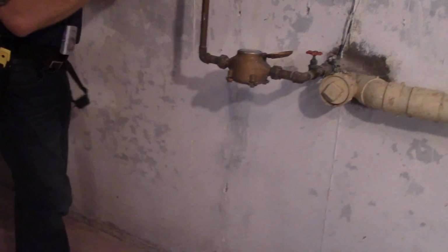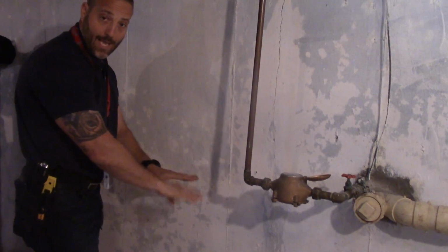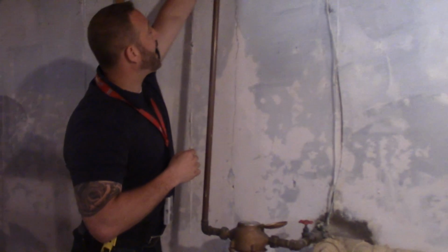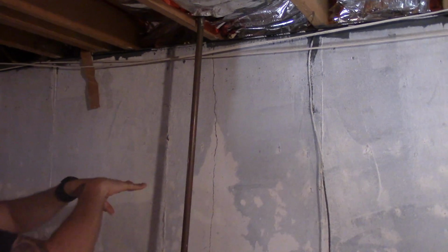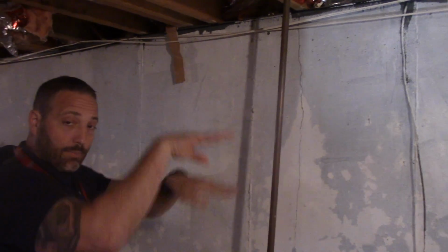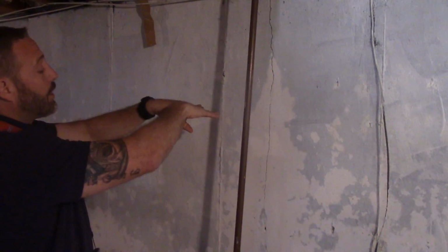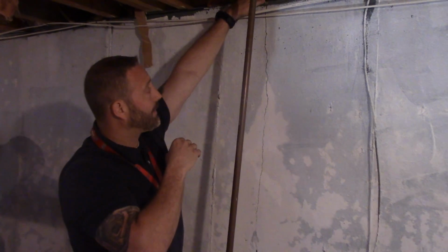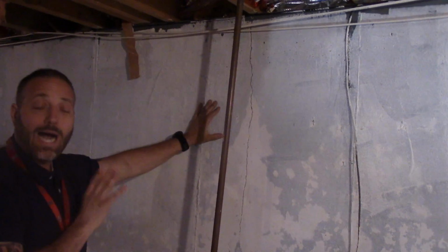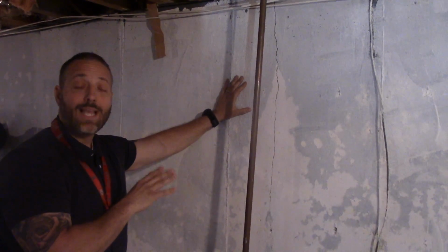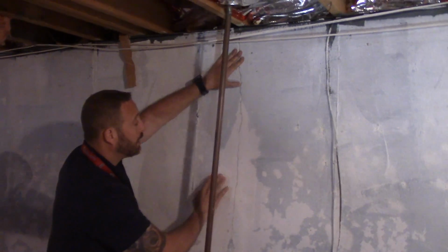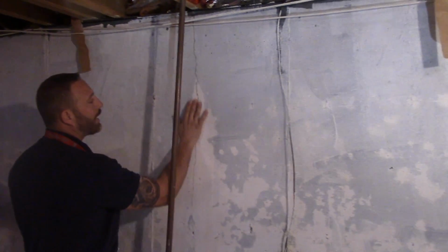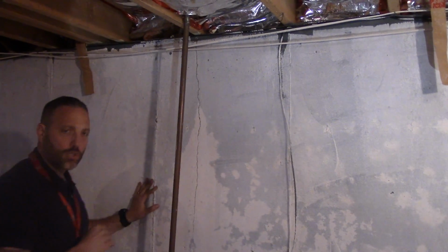Now, another technique to determine if the footer has been broken is by placing your hand up here on the top of the crack. If that section is flat and there's no displacement, that means your footer is intact. If your footer broke, there would be a displacement up on the top of the concrete. So, how would we identify this in the report? This would be a monitor, all right? Because there is no structural concern about this, but we do want to monitor if this crack is getting larger.